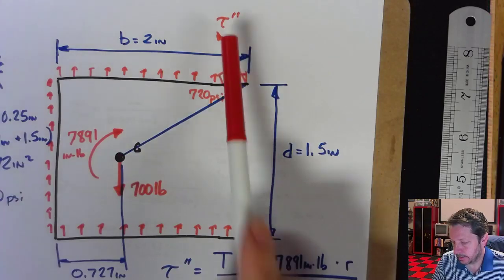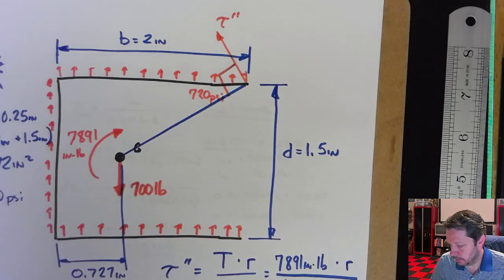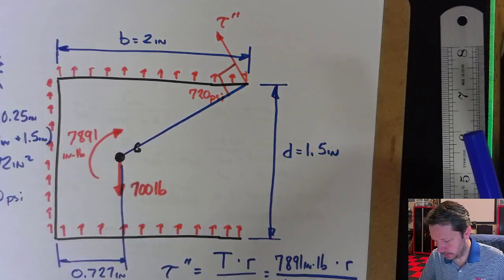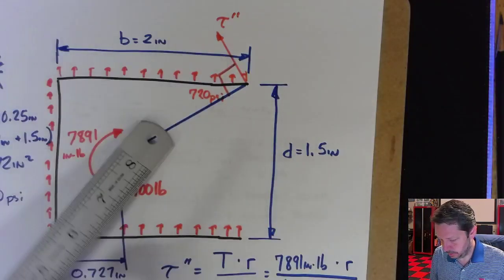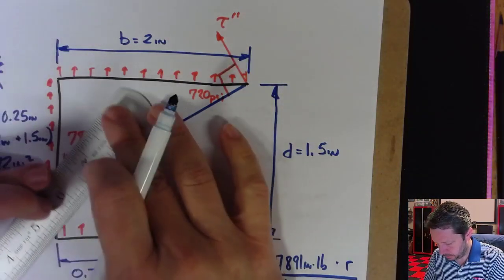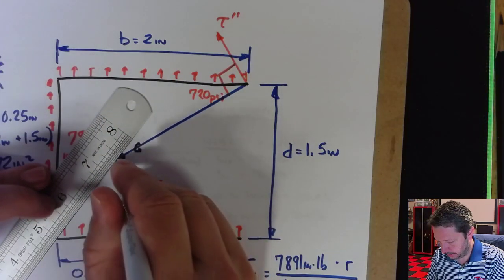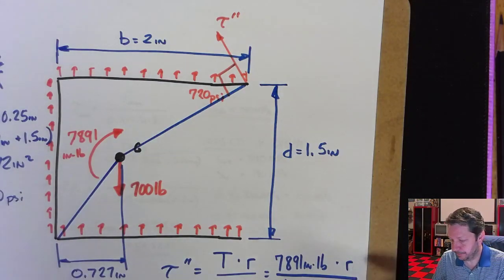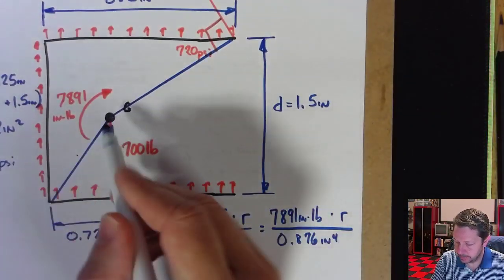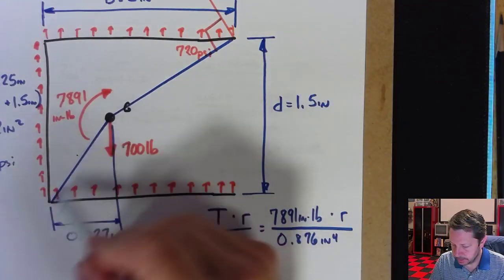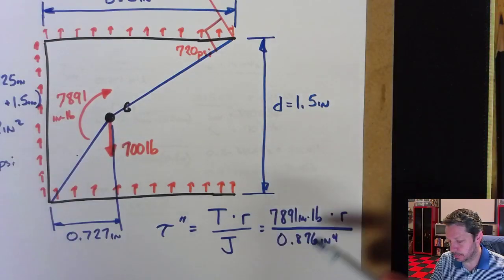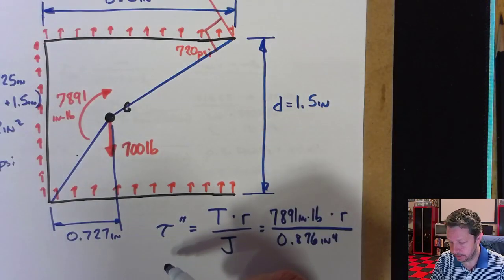And I can calculate that. Let's just draw another one just so we make sure we know. Let's do this one over here as an example. So here would be another R that I could put into my equation. This distance, again, if this is drawn to scale, is a smaller distance than that one, which would generate a smaller secondary shear stress.